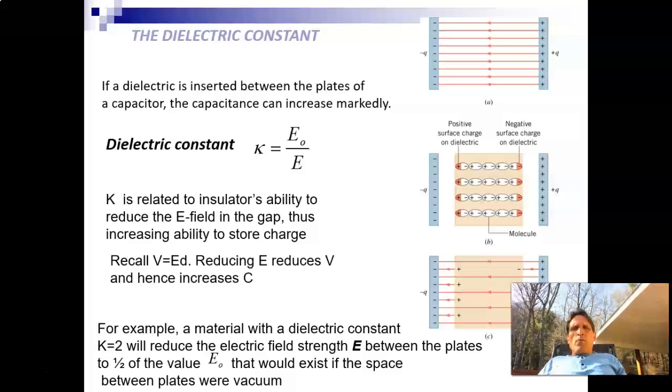So what if we want to store more energy? Okay, so if you have an air gap in between, and in practice we're limited as to how much energy we can store between the plates. But we can cheat a little bit, and suppose instead of an air gap, we put some polymer or waxed paper or some other insulating material, and we fill the gap between the 2 electrodes with an insulator.